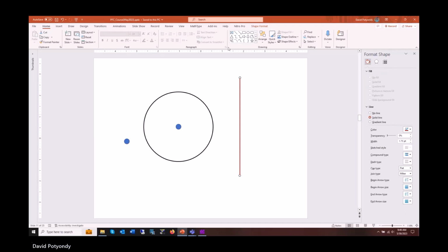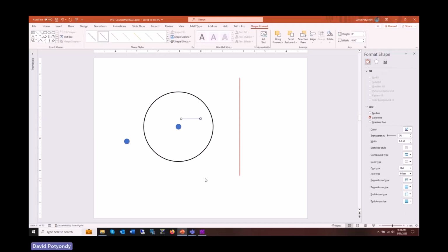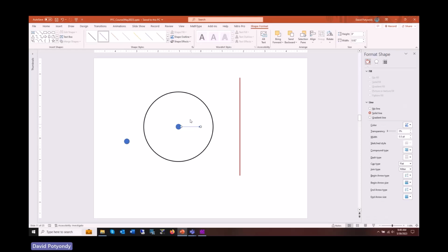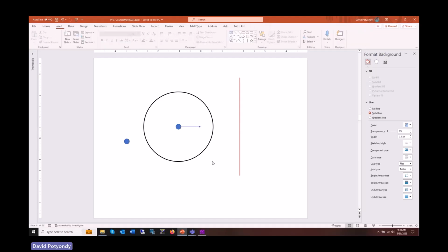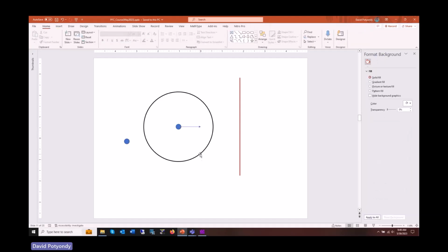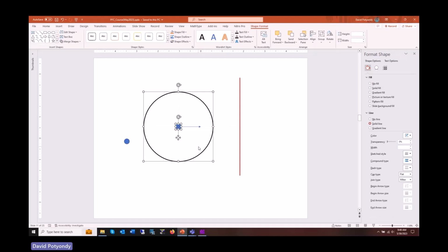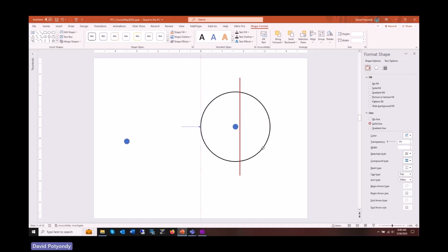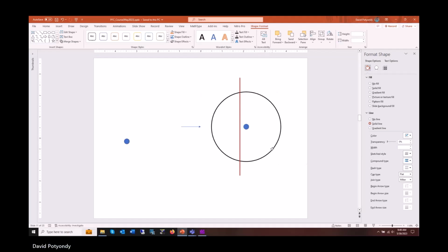here's my ball, and if this guy is moving at a certain velocity v, given the mass of this guy, it is going to begin to penetrate, reach some depth, and then go back. The higher this guy's velocity, the farther it's going to penetrate before it goes back. Okay? And the amount of stiffness here is going to matter. The lower the stiffness, the deeper the penetration. So because you have these high velocities with the high overlaps, it's possible that this guy is going to go, and the deepest penetration might be here, which means suddenly the contact goes to the other side and he goes shooting out.